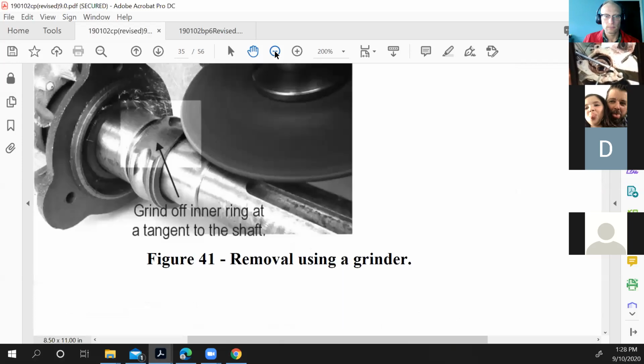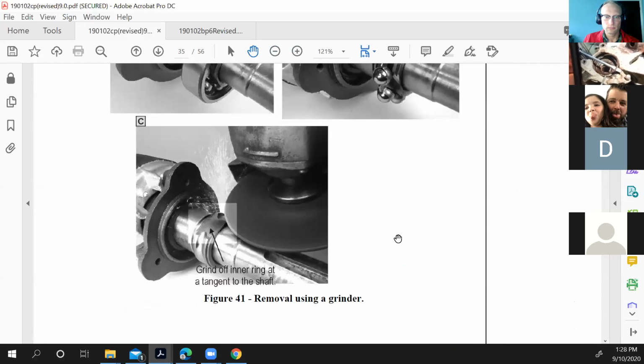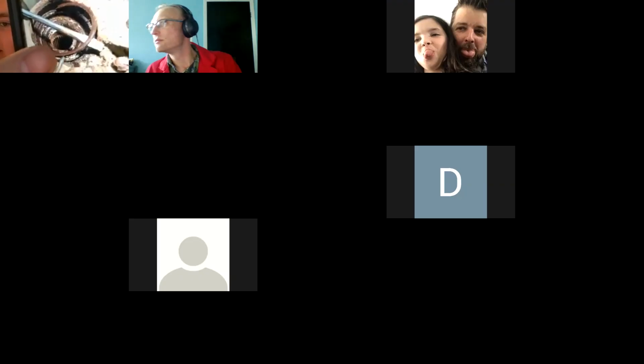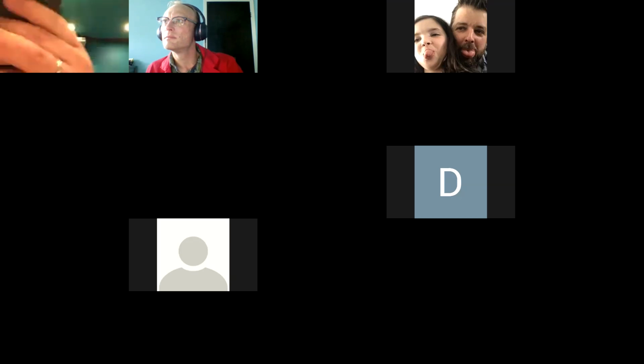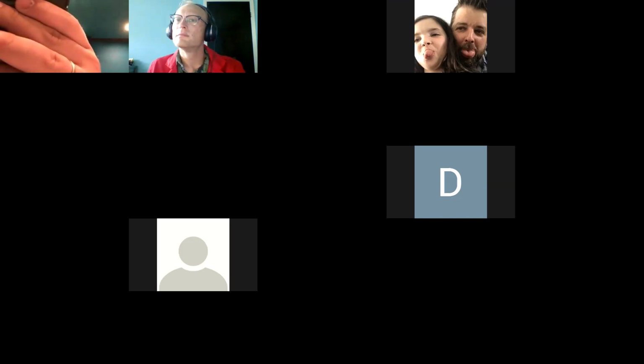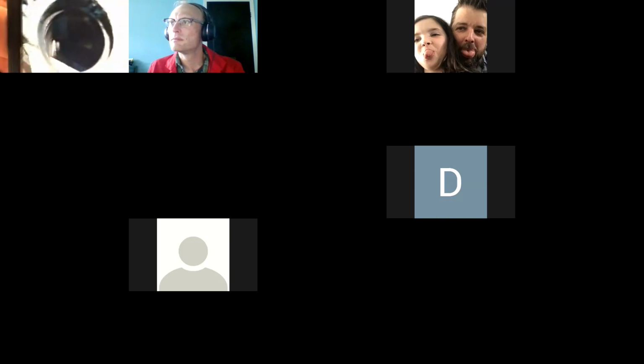What's that, Ryan? So this is the spindle on my wife's car. She's got an Altima. See, the big bearing in there is pressed into the actual spindle, and so I had to knock the center out, and then actually cut the race. Hold on here. There it is. Once I had the center knocked out, I actually had to cut this race with a plasma cutter to get it to release from the inside.